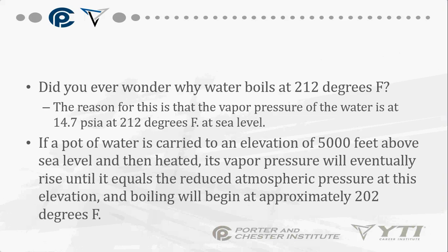At 5,000 feet above sea level, it will probably boil at around 202 degrees Fahrenheit, simply because the atmospheric pressure surrounding that water changes the way that substance is going to heat or cool. Which is how we're able to use refrigerant to heat and cool a space, by raising and lowering its pressure.